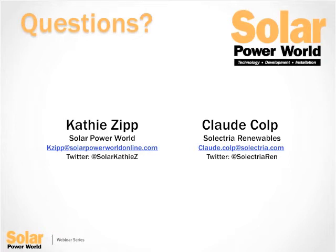And additionally, the way that the Solectria solution works for first responders is, no matter how you're powering the Arcom box, if a first responder pulls up to a burning building, they're going to do one of two things in most cases. They're going to either try to kill the power to the building completely, by pulling the meter, throwing the main disconnect, or going out to the actual power lines and disconnecting it there if they have the means to do so. In any of those cases, once the power is eliminated from the building, so long as the equipment is powered from the building, everything will de-energize, and it will create a safer environment for first responders.